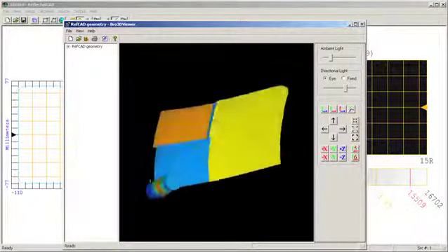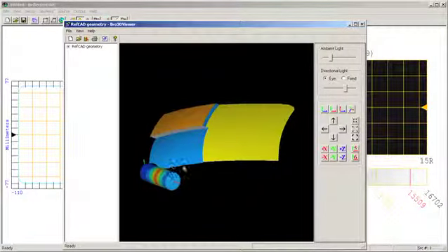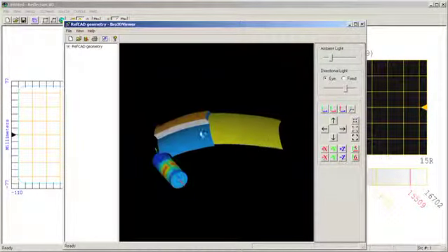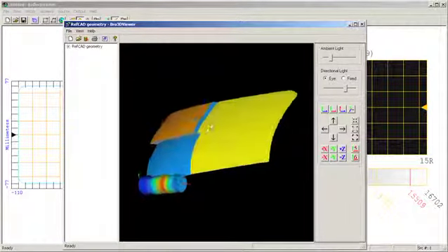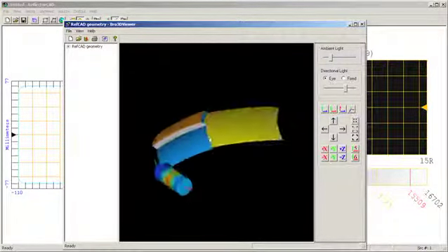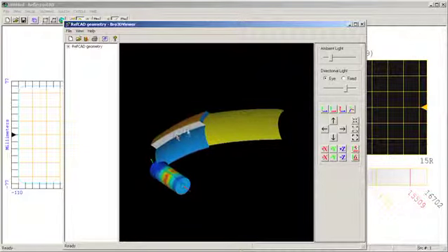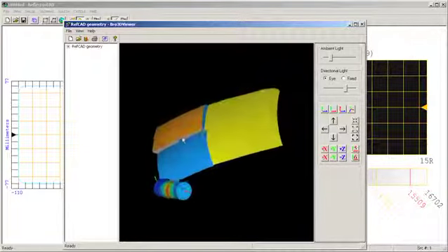You can see the three segments and the source down here. ReflectorCAD automatically puts in the inner segment fillers for me. I do have a small problem here that I have to correct in my design. First, this inner segment filler is much too large for production purposes.